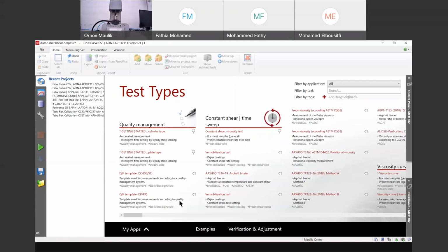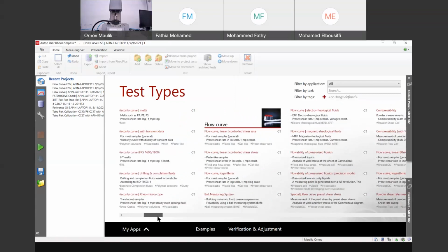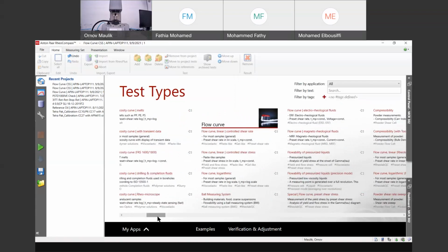Now, the first test what I want to show you is the yield stress test. The same test Dr. Fatia also mentioned about different various regions of any particular paste-like samples or crude oil, where first region you would always have an elastic limit. The second region would be more like a yield zone, where your sample would plastically deform.